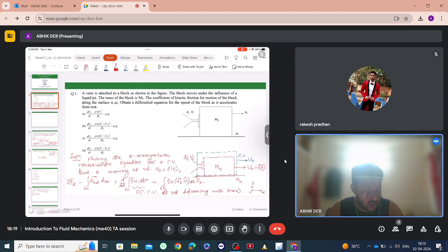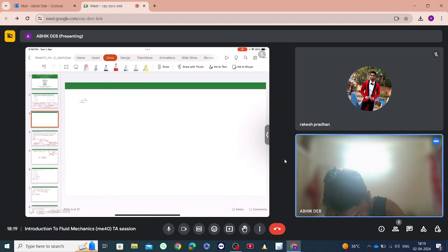So the friction will act opposite to the considered positive x direction, that is, along the negative x direction, and the friction force Fr will be equal to mu b multiplied by mb into g. Mb into g is the weight multiplied by mu b, which acts in the negative x direction. Okay, so we will have to write it as minus of mu b mb into g